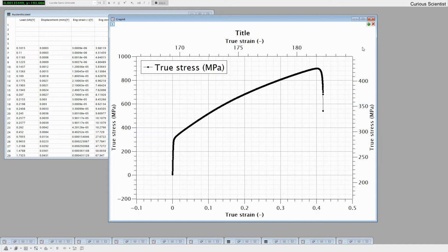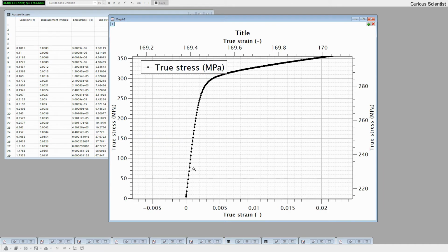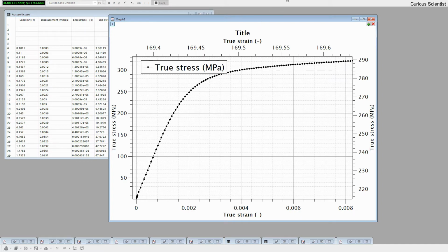So we came back to the curve which I showed you previously. So first let's evaluate the modulus of elasticity. So we just need this area right now, and we would like to get the slope between, let's say, 0 and, just eyeballing these things, 0.0014.